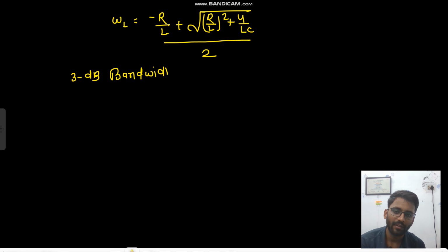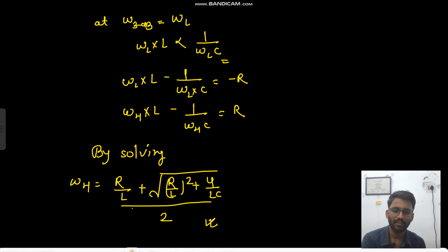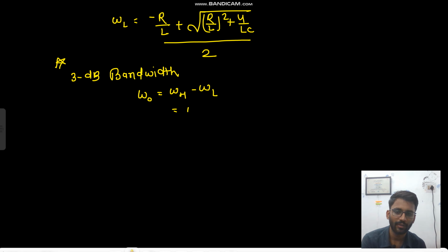The 3 dB bandwidth will be omega H minus omega L. This value minus this value equals R by L. So that you should remember.